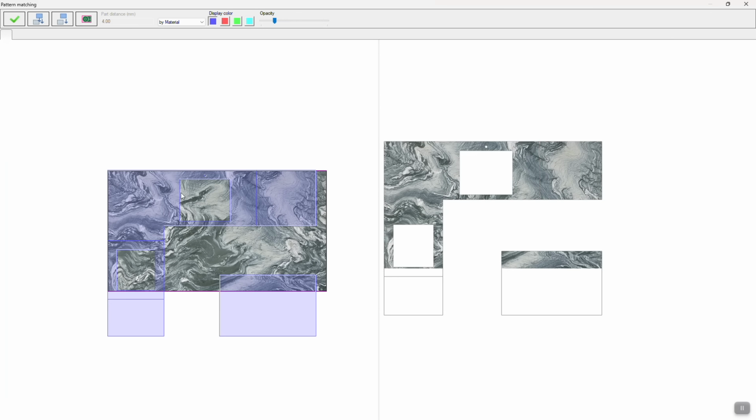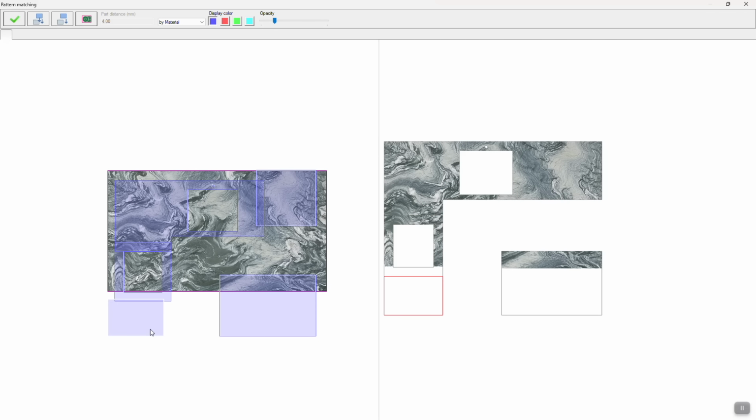And now you see we have this layout here. It matches this layout, and we can click and drag these things, and we can click and drag these things. We can right click to rotate them. But I can also nest here, and I can use our common cut toolpath by using the tool diameter as the part distance.